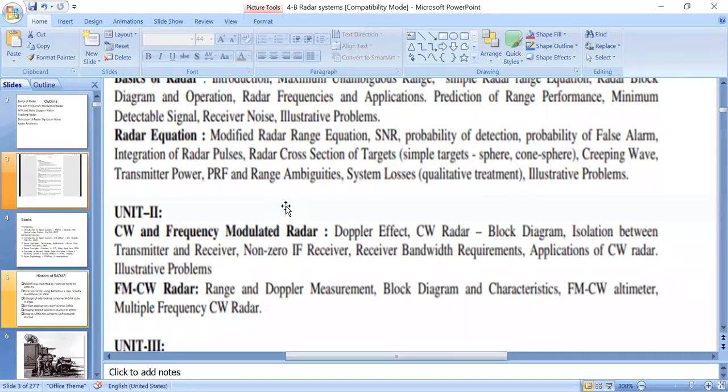I will recall all the concepts. Please try to concentrate. I'll give tip points, right? Whereas coming to pulse radars, we have two types: basic pulse radar and moving target indication radar. In basic pulse radar, the transmitted electromagnetic wave is a pulse wave, and it is used to identify only stationary targets, not moving targets.